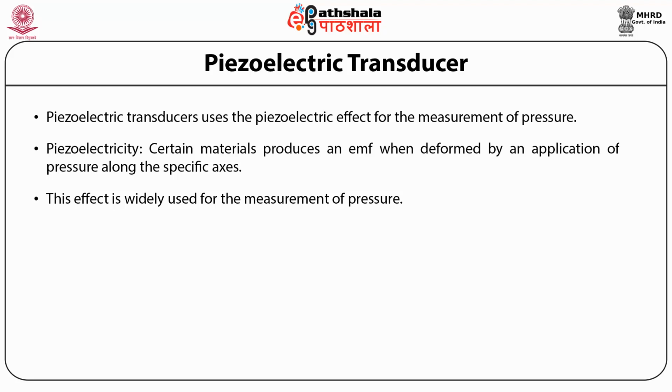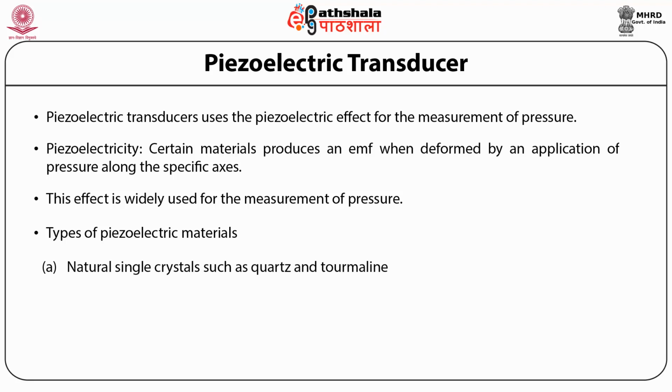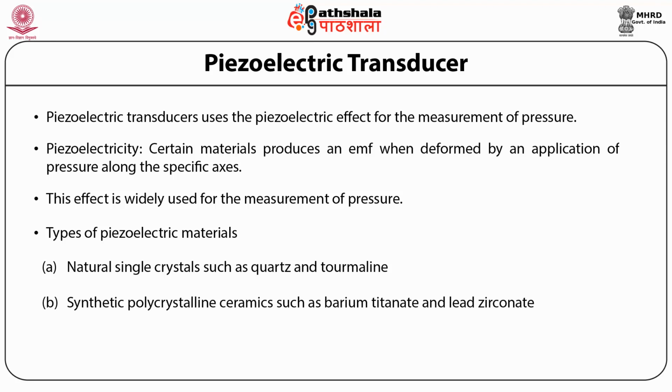A piezoelectric crystal should have a charge asymmetry, that is, the center of the positive charge of the crystal does not coincide with the center of its negative charge. There are two types of piezoelectric materials. First is the natural single crystal such as quartz and tourmaline. Second is the synthetic polycrystalline ceramic such as barium titanate and lead zirconate.